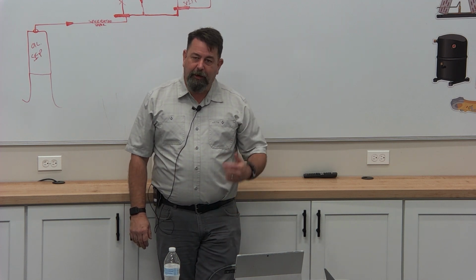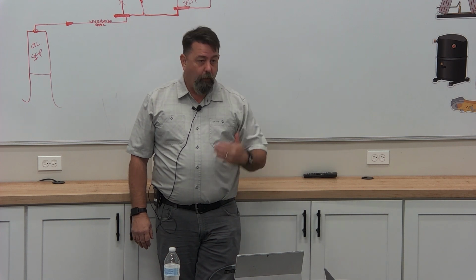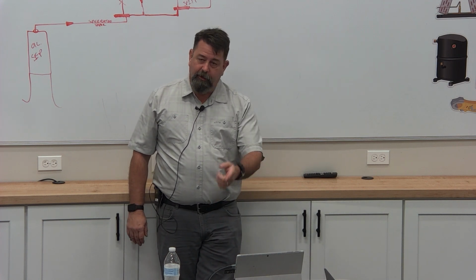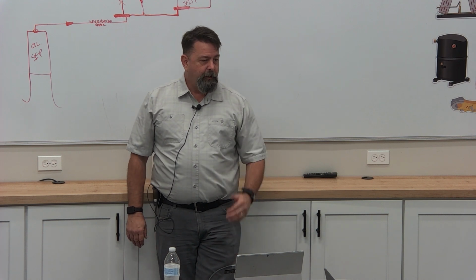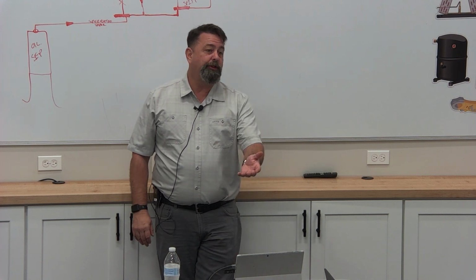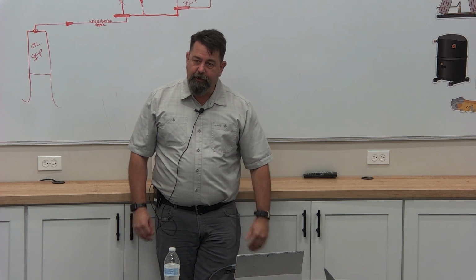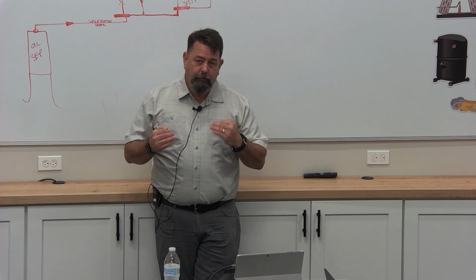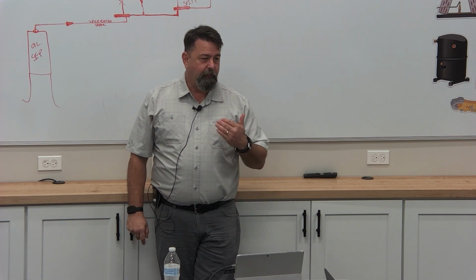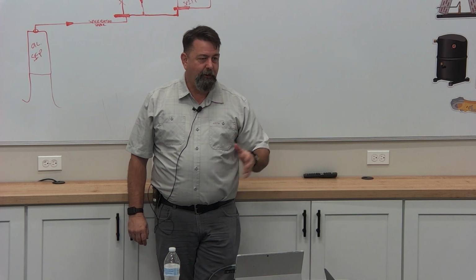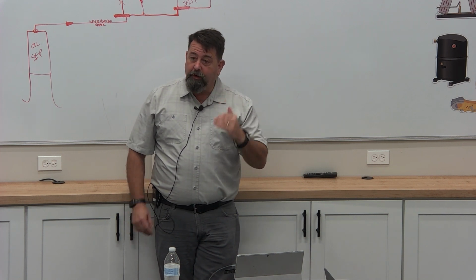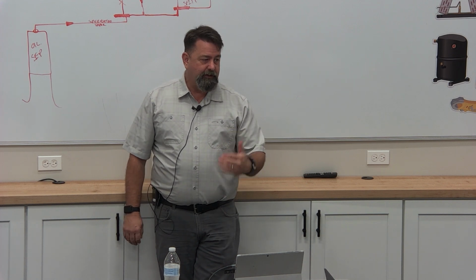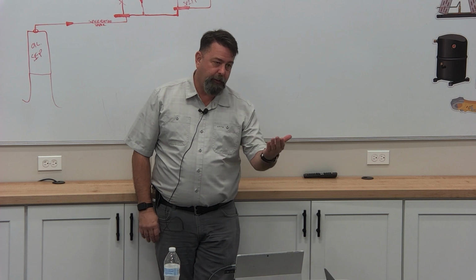Their core product temperature is not good. If my case is running not at alarm, but warm, that's what this will create. I'm not gonna trigger an alarm on this, right? But if this case is supposed to run 32, it's running 35, 36 degrees. Not enough to trigger an alarm, but my core product has got to be below 41 degrees always. Food safety, core product, that's probably a whole other class. 41 degrees even in defrost. If this thing's sitting here at 35, 37 degrees, my core product's probably in the mid 40s.